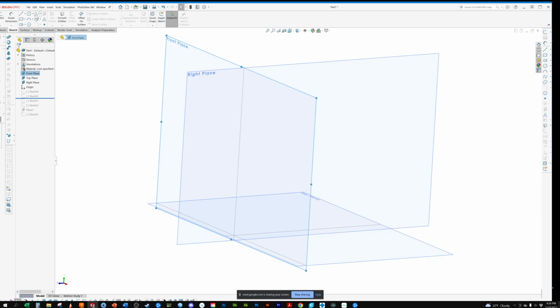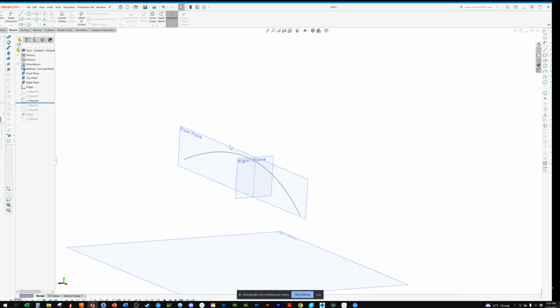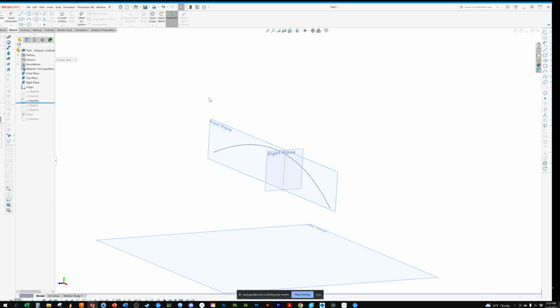Now, we've already spoken that a lot of SolidWorks is on sketch planes, and we'll also get into using 3D splines when appropriate. But to create surfaces, there's going to be a lot of planes to build. So I want to create a loft, so that means I need to have at least a start and an end point. So I'm going to go Insert, Reference Geometry, Plane, and we're just going to create a plane. Sorry, I'll walk through every step that I do. We're going to go Insert, Reference Geometry, Plane.